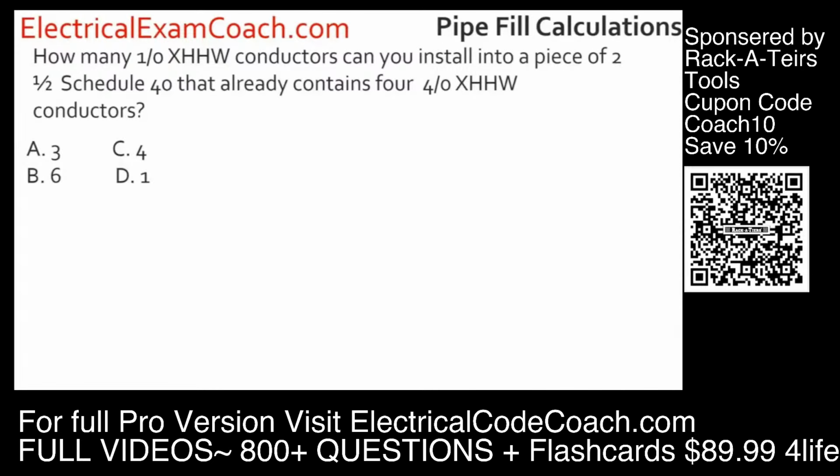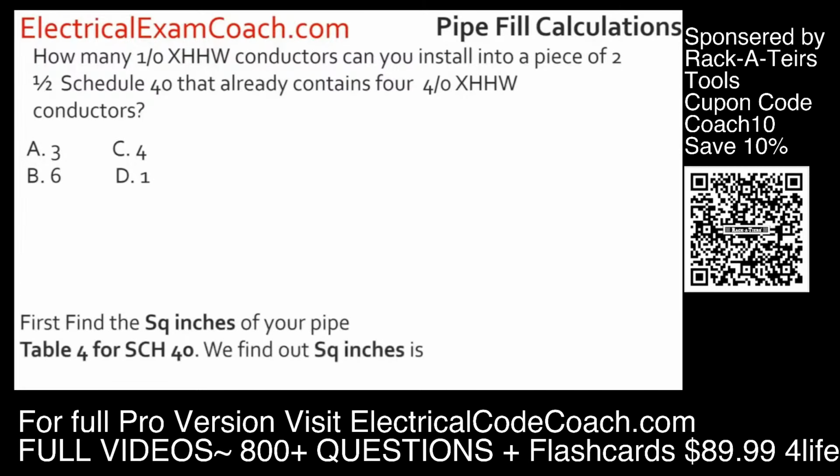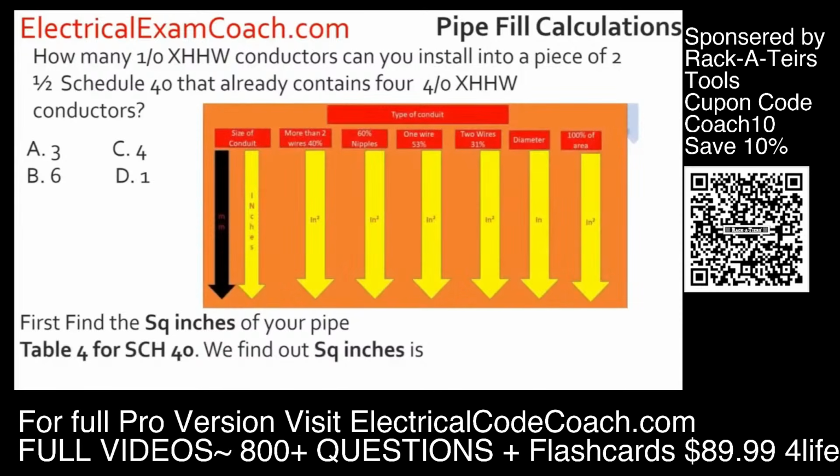How many 1/0 XHHW conductors can you install into a piece of 2.5 inch Schedule 40 that already contains 4 4/0 XHHW conductors? The first thing we're going to find out is the square inches of our pipe. For that, we head to Chapter 9, Table 4, for Schedule 40. When we get there, we first verify that we are in the right type of conduit. Then we come over to the left and find our size of conduit. Then we come over to the 40% column because we have more than 2 conductors, and we find that for this conduit, it's 1.878.